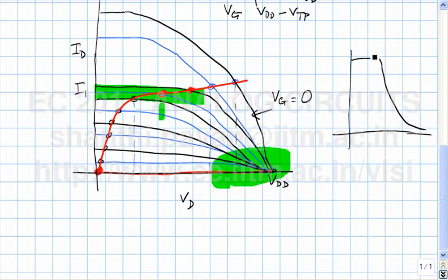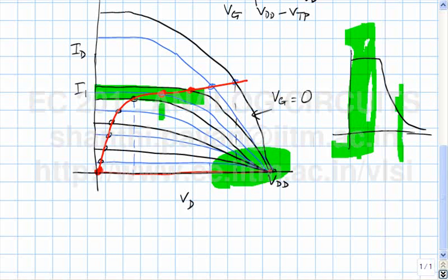The inverter. Find all input voltages less than a certain voltage to be your logical 0, and all input voltages greater than a certain voltage as a logical 1, then this defines a digital gate. This is a NOT gate or the inverter. You understand? The digital guys are terribly excited by the flat portions of the curve.